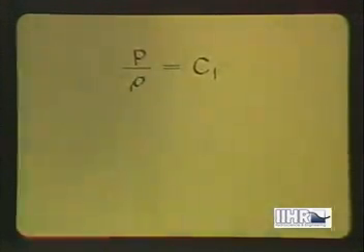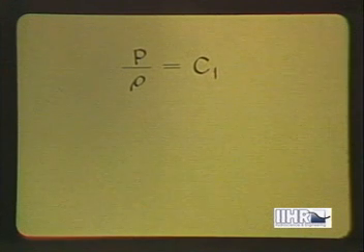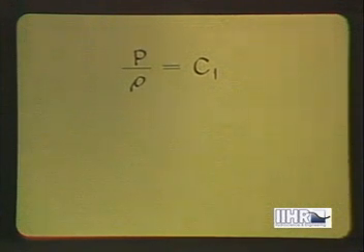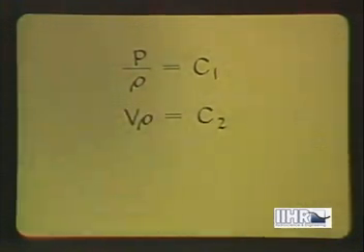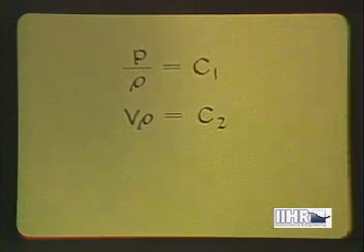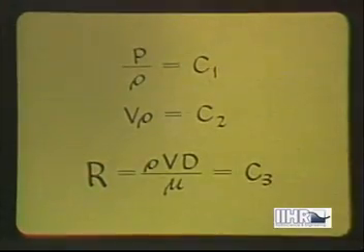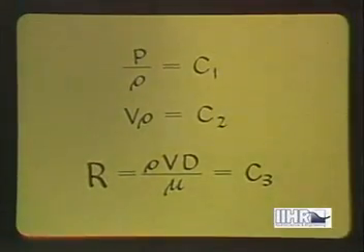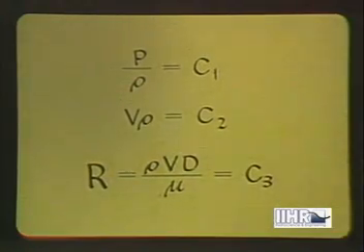So long as the density changes are small, elastic waves in gases differ little from those in liquids. When the density changes become appreciable, on the other hand, use must be made of the gas equation introduced in the first film. For isothermal flow through a long pipe, the density will vary directly with the pressure, and the velocity inversely with the density. Therefore, even though the pressure decreases because of the wall resistance, the Reynolds number and resistance coefficient will remain constant.